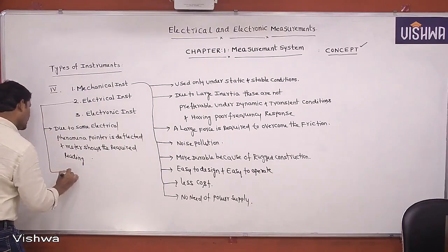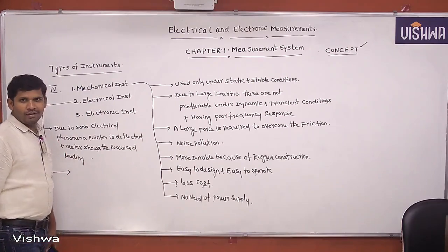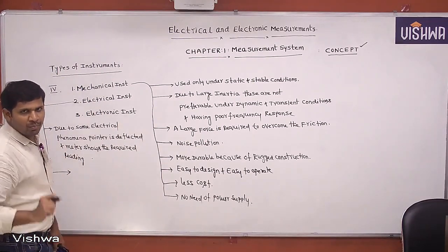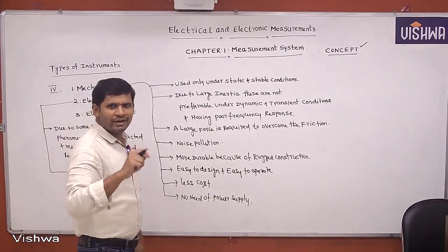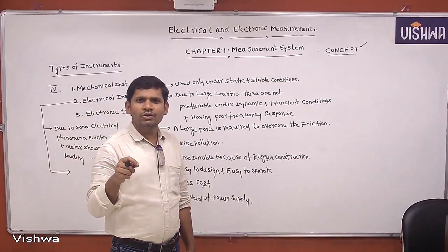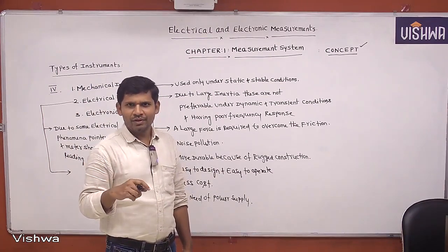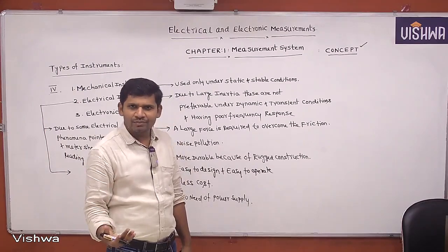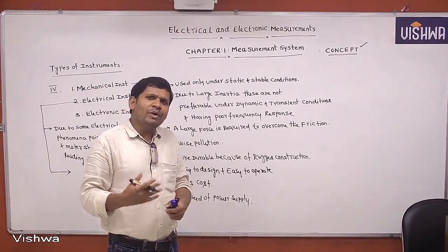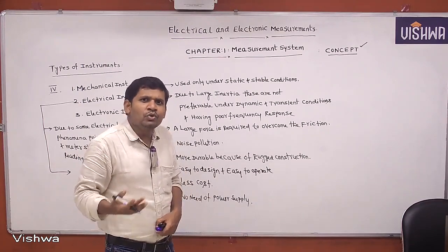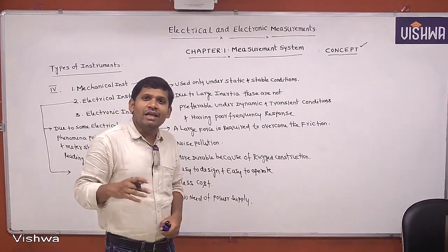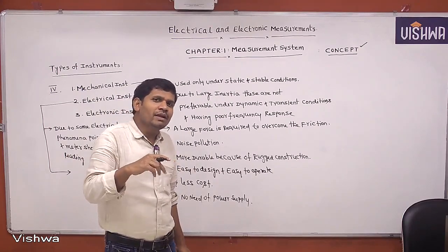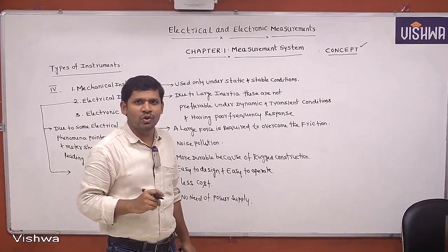But the point to remember here is that even in electrical instruments, the moving part, the pointer, is also a mechanical element. Because of that mechanical element, it has some inertia. Hence even electrical instruments have inertia, and due to that they offer less frequency response. But as compared to mechanical instruments, it is a better frequency response, no doubt at all.